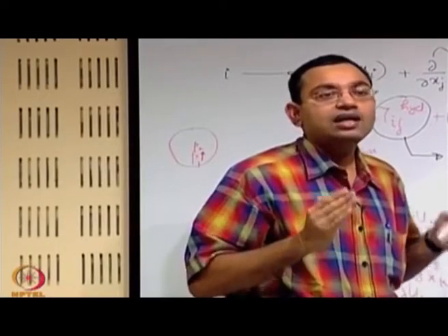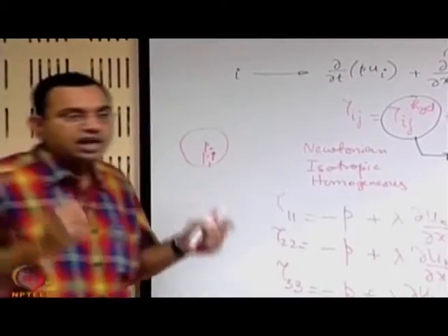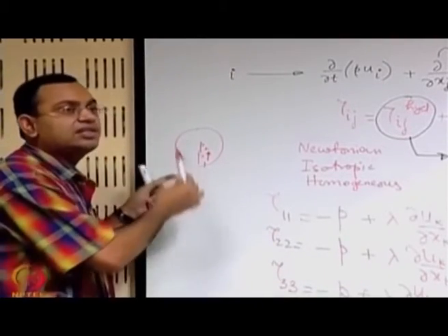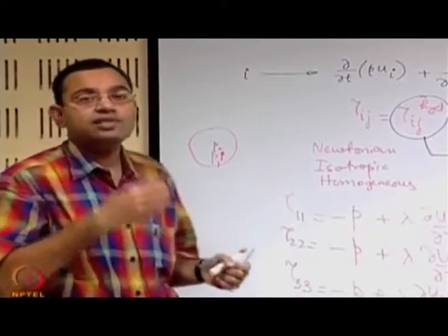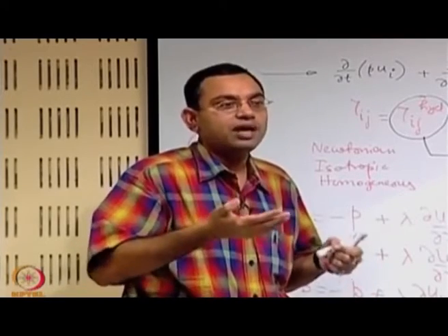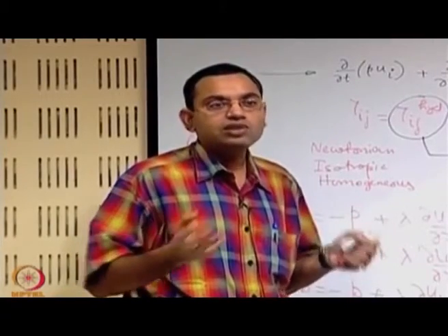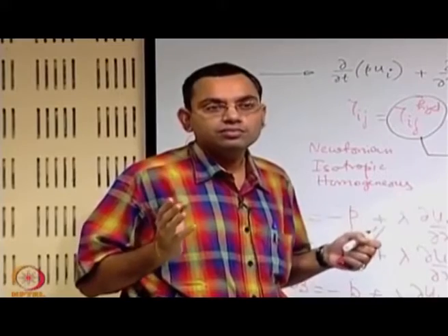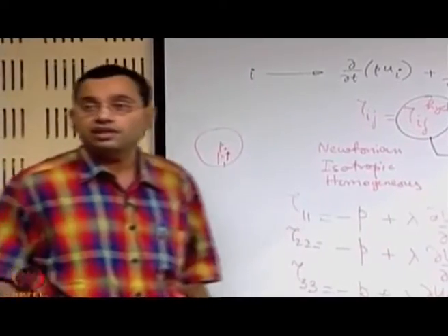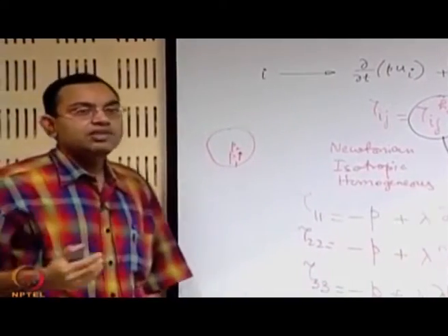So this is called the relaxation time. The relaxation time is very important. What is a relaxation time? You have a system, you are imposing a change to the system, and the system must have sufficient time to absorb that change and have changes in properties by local equilibrium, by having a new state of local equilibrium because of that change. So it should have a time over which it changes that state of equilibrium. It cannot be instantaneous. Because it cannot be instantaneous, there is a time scale which is called the relaxation time scale.